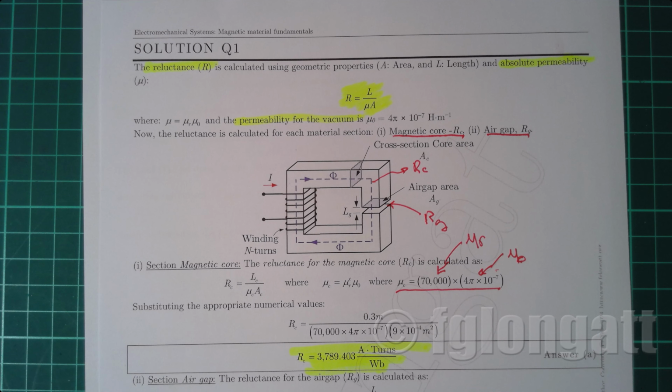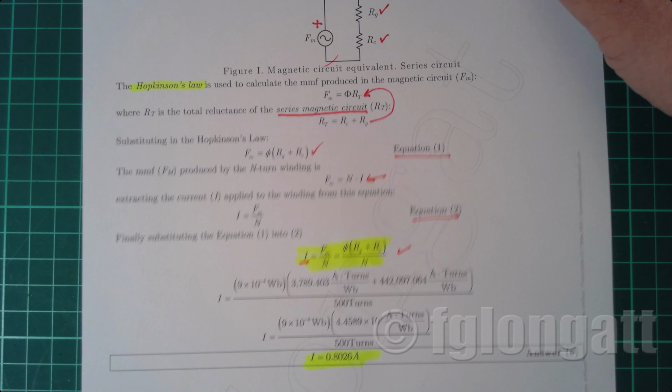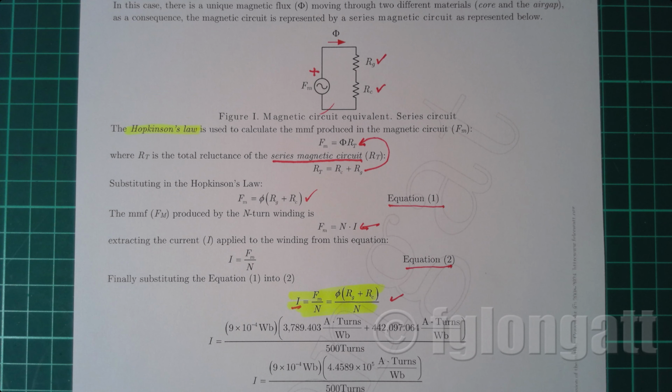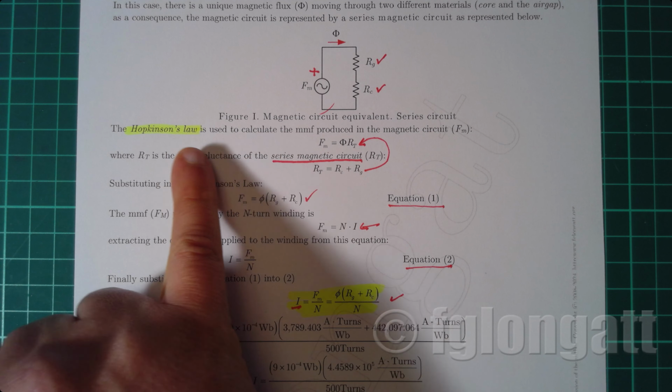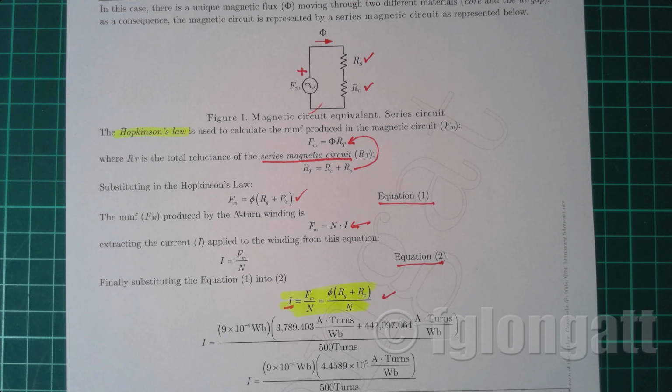And we also learned that any physical configuration establishing magnetic properties can be represented by something we call magnetic circuits. And from a magnetic circuit, well, all my students are extremely clever, they understand circuit analysis for electrical circuits, so they can do something similar for magnetic circuits. Instead of using Ohm's law, we will use Hopkinson's law, and the problem is solved in that sense.